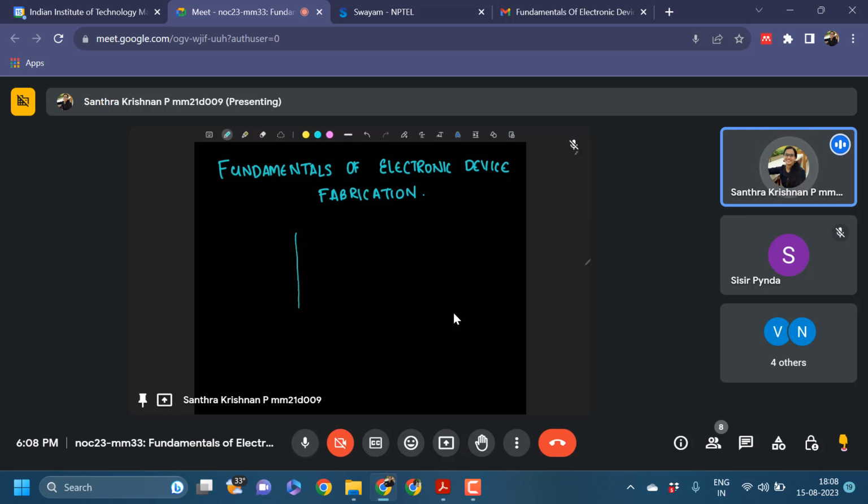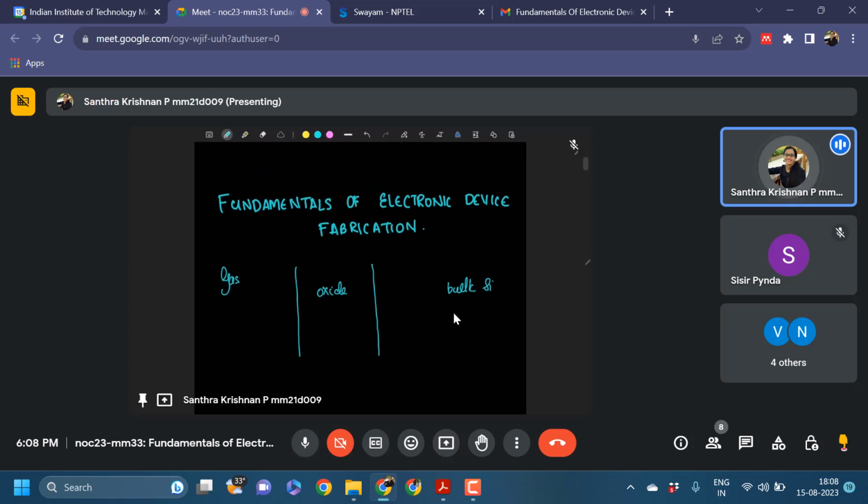We are considering two interfaces. So this is the gas phase. This is the oxide layer that has already been formed, and this is the bulk of the silicon. Let us assume that the concentration of the oxidation species here is Cg, and on the surface let it be Cs. So we are considering a thicker surface, and here let us assume that the concentration is C0. And at the interface of the oxide layer and the bulk silicon, we have a concentration of Ci.